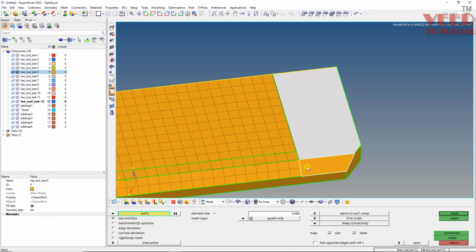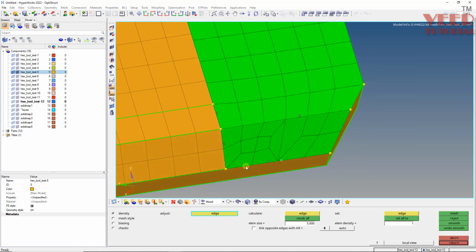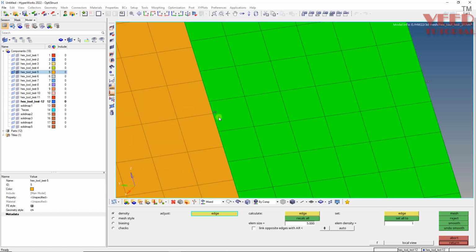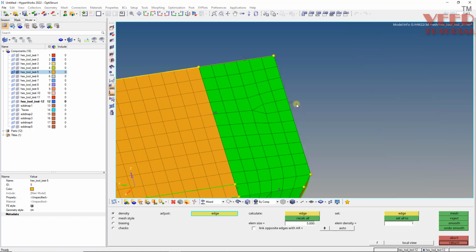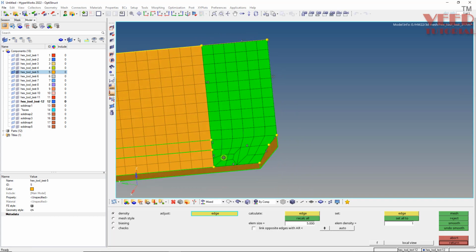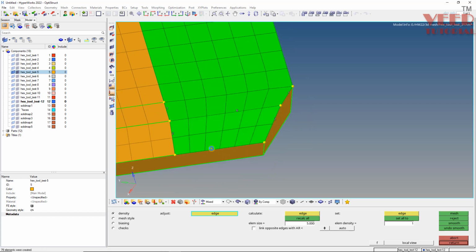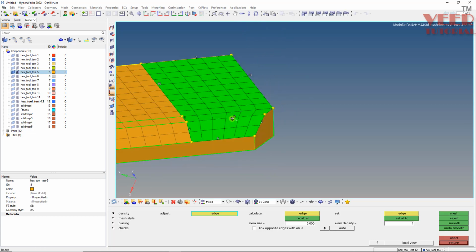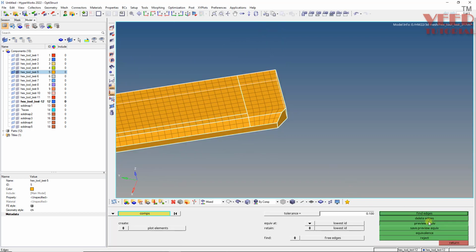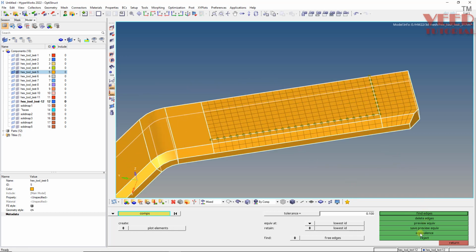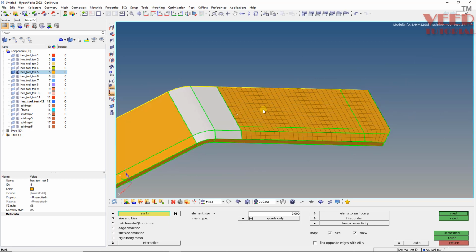Now pick up this right one, and here you can see the mesh flow is not good, so we have to change some setting, but here it is not connected, so let's increase the value or let's say decrease the value. Okay, 10 is working here, make it 10. Let's say I will increase up to 6. Okay, it will work. Now we have to equivalence them. Shift plus F3, select component, preview. So just equivalence them. Now continue to do this in the remaining part.